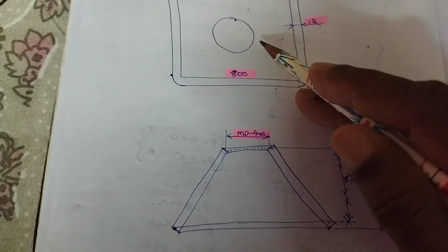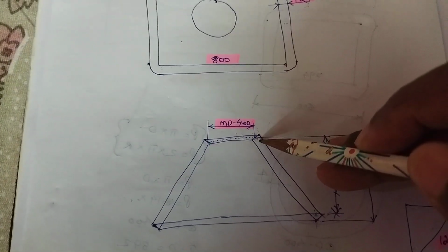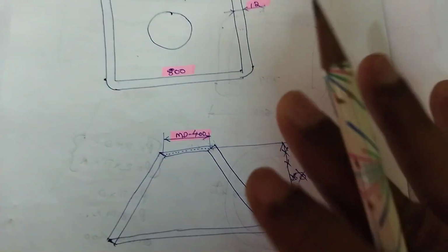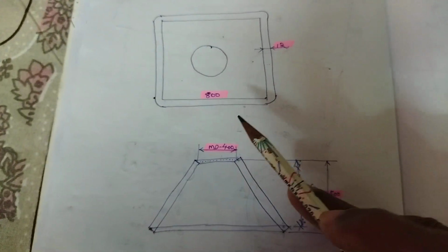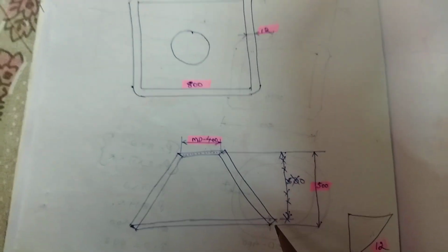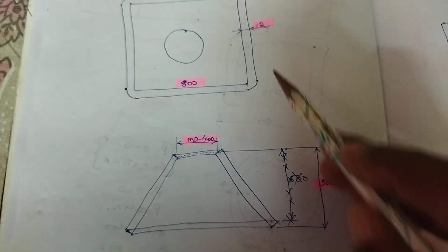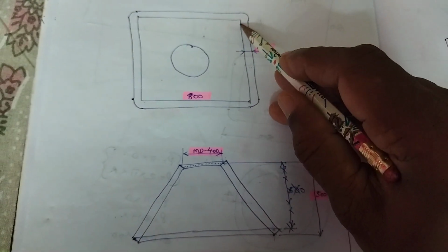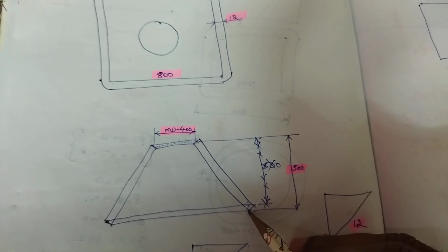When its top side is round, it has a medium diameter (MD) of 400. When we calculate these kinds of jobs, square to round jobs, if the measurement is like this, always there is a round portion, a square portion, and a bent portion. For the bent portion, true lengths have to be taken from this corner to this corner. It means that corner is this one. This is that corner.